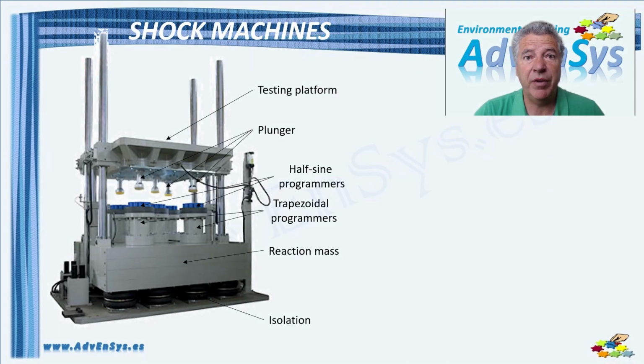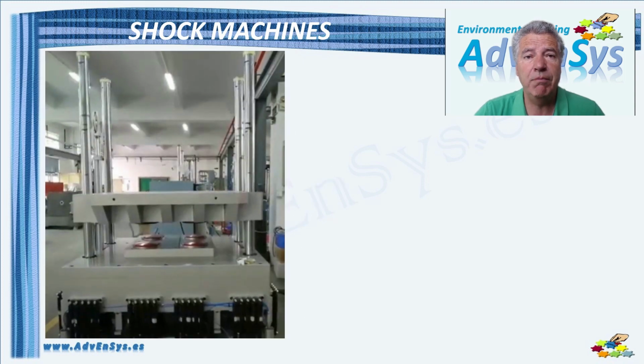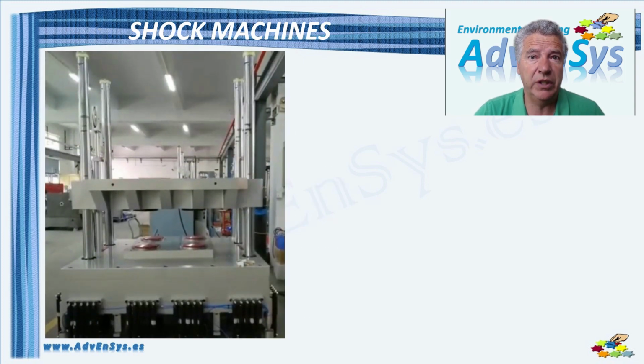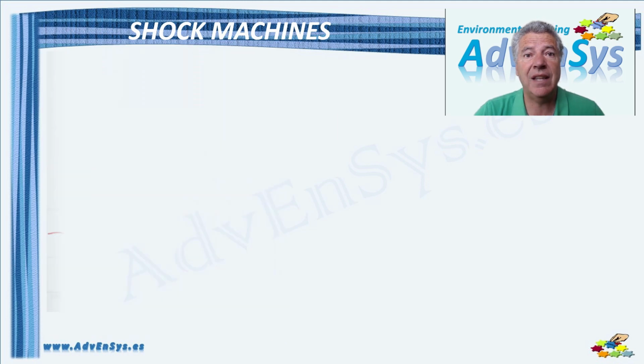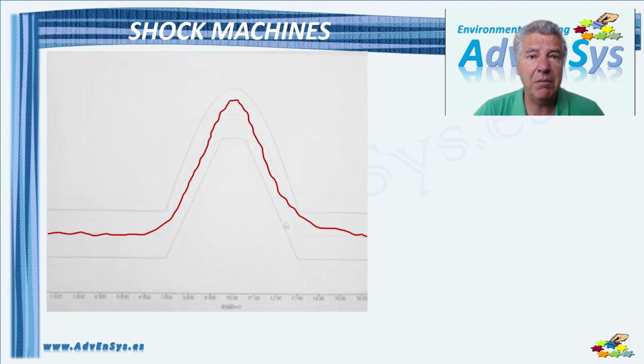We can use two different types of equipment to reproduce classical shocks. The shock machine includes a table where the DUT is fixed and is raised up by a crane. The height will determine the amplitude of the shock. Then it's left to drop down free, impacting on some elements called programmers. Depending on the type of programmers, we can get different shapes and duration. The equipment has a very heavy reaction mass to minimize force transmission to the surroundings. The signal we record is acceleration as a function of time, similar to the example in the image.